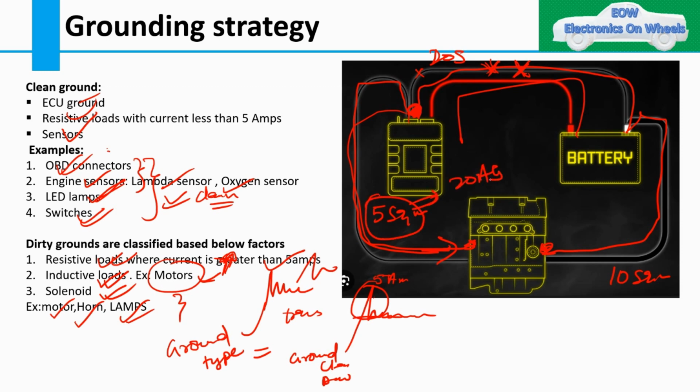But when this particular ground wire is not working, there would be chances that all the loads which are connected here will pass through this, and your wire will burn. Suppose I am taking all the return path from this wire, and you have designed it for 20 amps for 5 square mm, but because of the failure of this particular wire, all my ground is taken from this. Then what will happen? Suppose 40 amps of current is flowing through this, then your wire will be burned out.